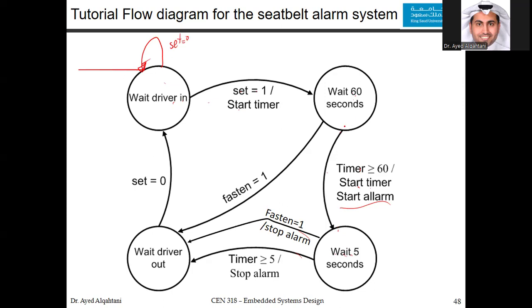So in the system, here, if you are waiting 60 seconds, you worry about the second input. Did he fasten or didn't he fasten? If he fastened, it means everything is fine. We don't have to sound the alarm. And we go to this state, which is waiting for the driver to get out.